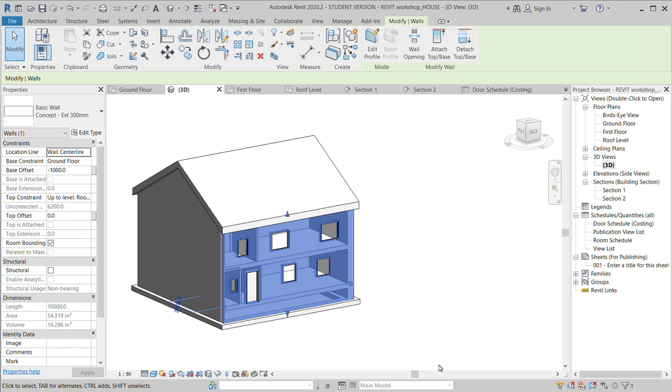So you can either have the complete specification of a wall and know how much it costs to build that wall per meter squared, or per meter, in which case you can multiply the area of a wall within your building by that unit. So you've got to generate your own units, and typically with walls it's a unit per meter squared rate that's applied to the construction of walls, roofs, or floors at basic level. I will show you in the next tutorial how you do the material takeoffs, which is slightly more complicated, if you don't have the overall cost of a wall per meter squared as constructed.